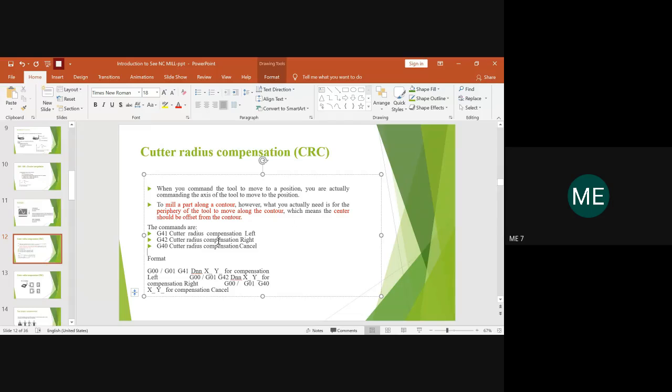But it depends upon the compensation you give so that it will make the contour as required. It can move in the x direction, again y, x, y, x, y within the given blank to make the contour. To make the tool move properly, it has to be compensated with some value so that it makes the contour easily without causing any harm to the periphery.